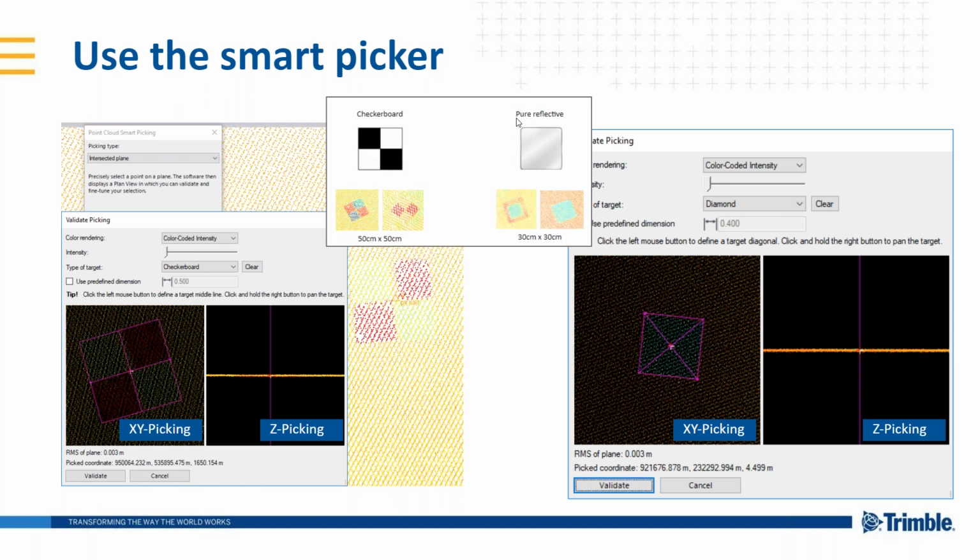If it's like a manhole, sometimes the point cloud goes under the surface. So if you're picking the wrong Z, that of course would not produce good results. So we've split this target picking into an XY picking and Z correction. And that's the way to measure the targets very accurately on screen.